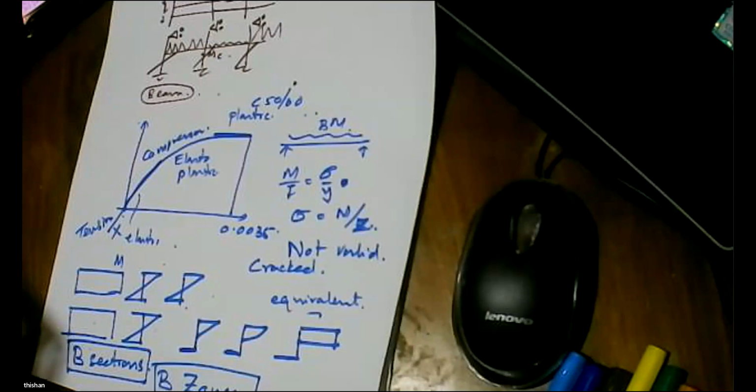Without high end bearing, our pile capacities are very low. For example, a 1200 pile can usually carry a 6500 kilonewton load, but it is now carrying only 4200. A 1500 pile can generally carry 10,500 kilonewtons, but in this particular site it can carry only 6500 kilonewtons when you do all the calculations according to the geotechnical engineer.